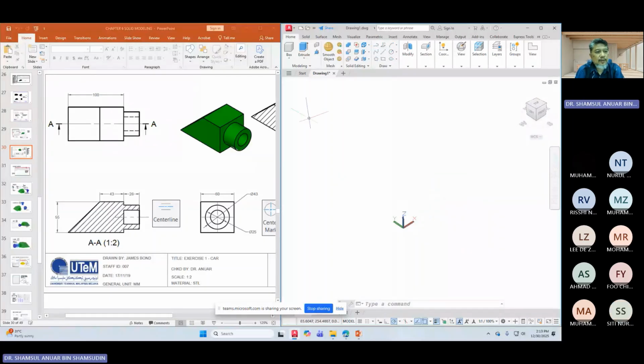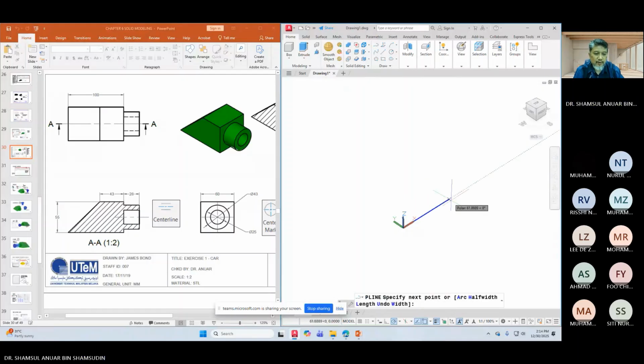Okay, so can we start from here? If you want to go look normal to it, you can click here, or if you want to draw from this angle, that also works. So you click on polyline, then click 0, 0 or type 0, 0, hit enter, point to the x-axis, to the positive x, and type 100.